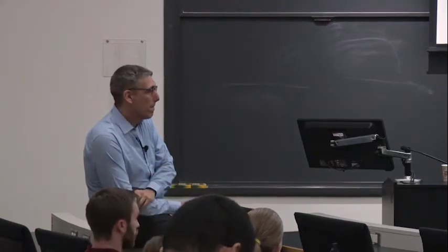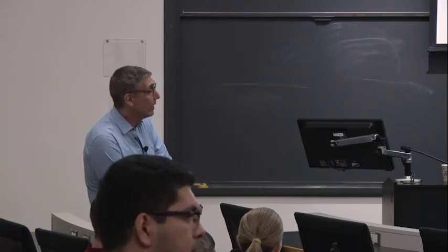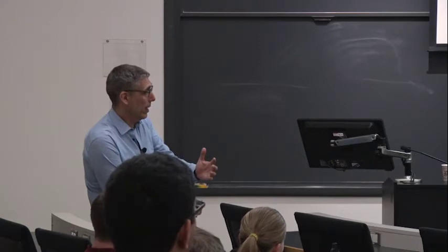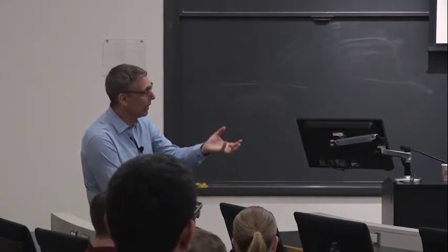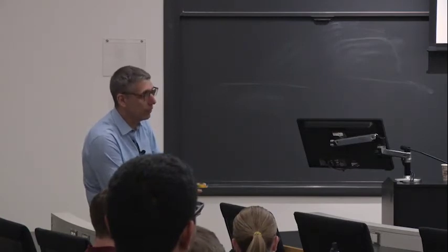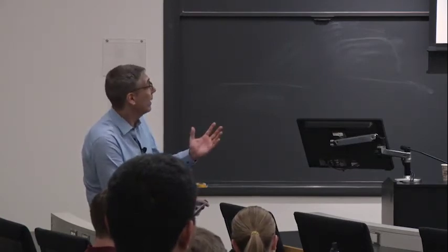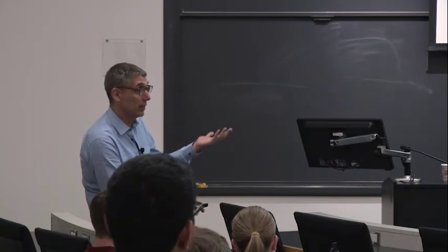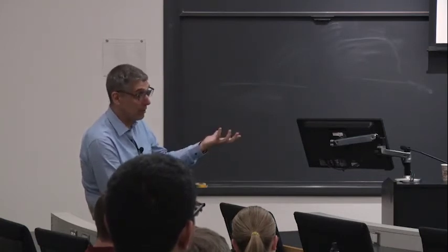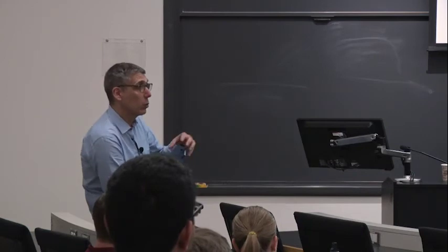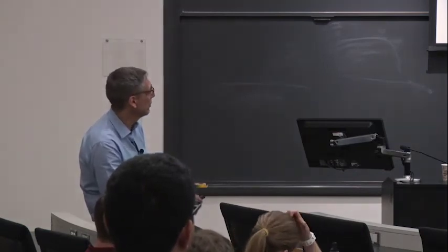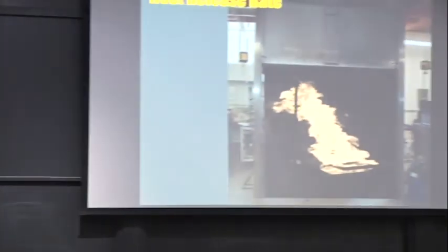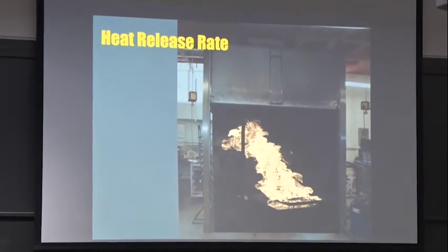Gasify easily. That's exactly what it is. So basically, it breaks extremely easily. So you have a very large amount of fuel that comes in, a very high temperature of the flame, a very, very strong value of Phi. So in a way, this becomes a bit of a surrogate for the decomposition chemistry. And it gives you a sense of which one is a vigorous decomposition chemistry and which one is a weak decomposition chemistry.